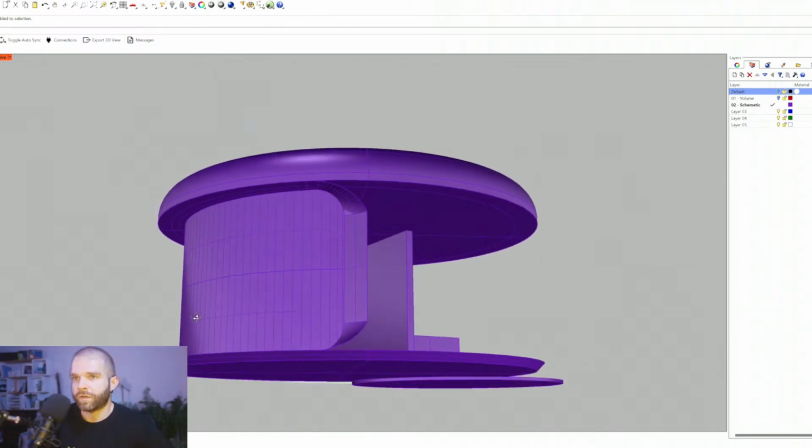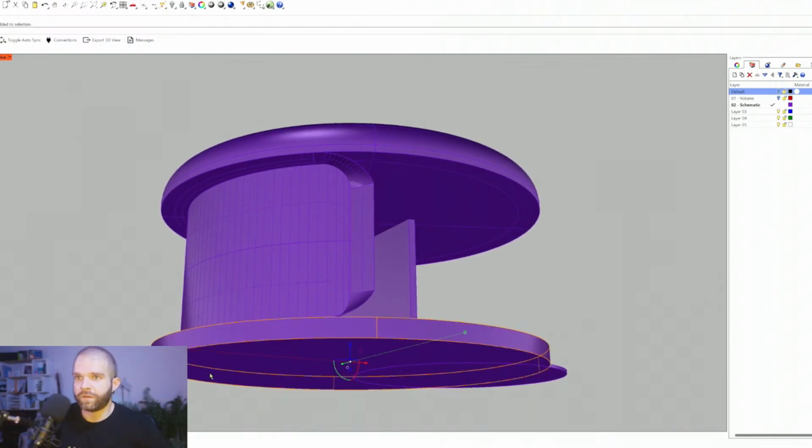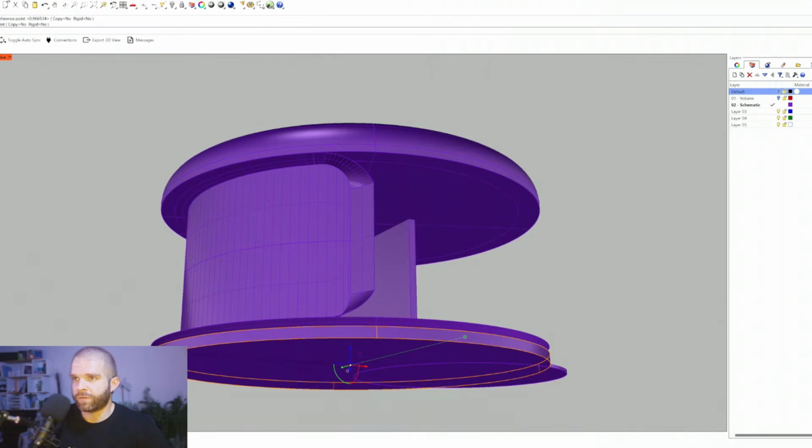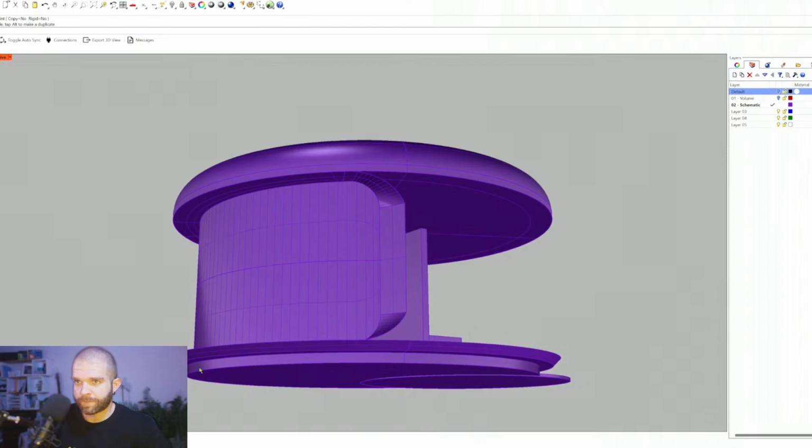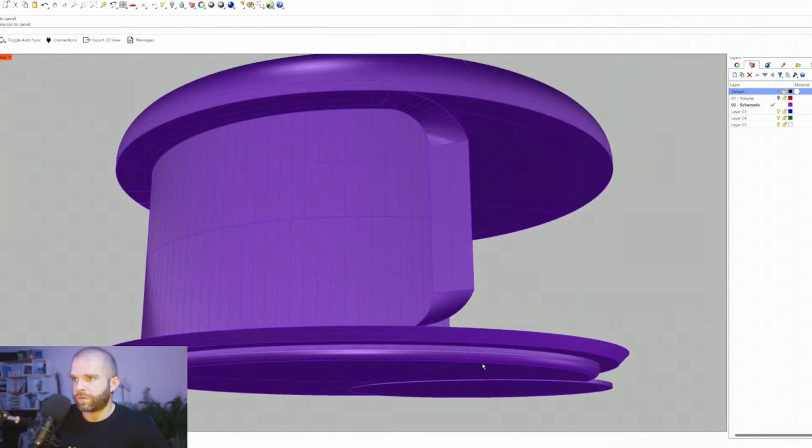Okay, so that face scaled in. I'm going to take this face, scale 1D, and bring it down to the others level, scale it even more, right? And then fillet edge that bottom. We'll do a radius there of, I don't know, 6 inches. Oh, that didn't change. Next radius, 6, yes? Yeah, that's good.